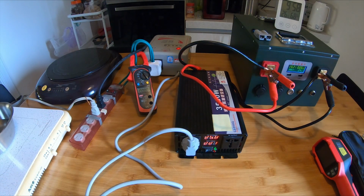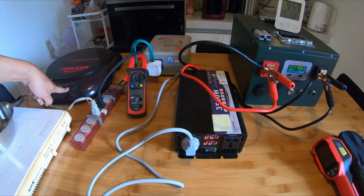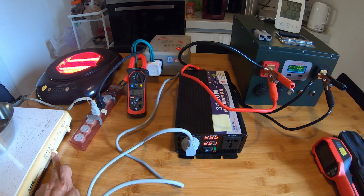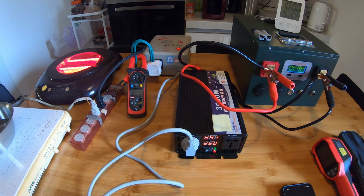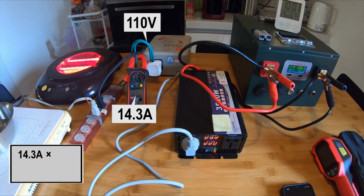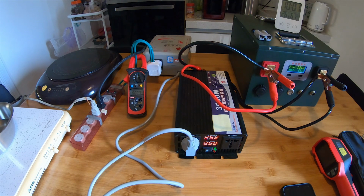After repairing the inverter, re-observe the real power of the inverter. After switching on the maximum power of the ceramic stove, the meter measures the inverter output with a current of about 12 amp. Turn on the induction cooktop to increase the load power. The AC current is now about 14.3 amp and the voltage is about 110 volt. This means that the actual continuous power consumption is about 1573 watt. After less than a minute, the inverter stopped working due to overload.